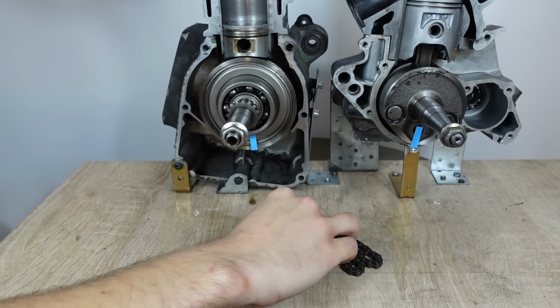As you can see, I need some strength to overcome the resistance of the valve spring and open the valve. This strength must come from somewhere when the engine is running, and so the valves actually steal a bit of the energy created by combustion to open themselves and allow the next combustion to happen.